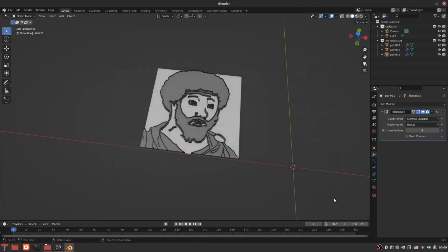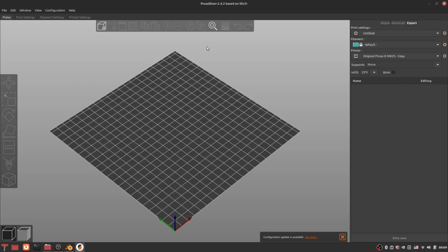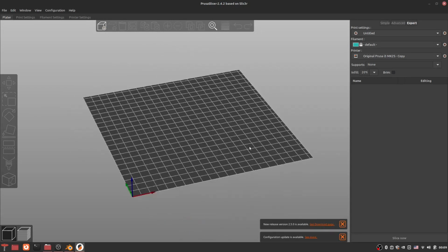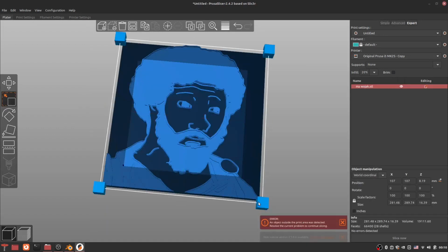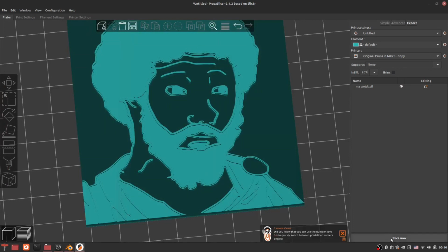The model is ready, but it'd be nice to check if everything is alright, so let's open Prusa Slicer. I will, you might enjoy something else. Here we don't care about optimal print options yet, we just want to check if the model is readable and is interpreted correctly. So let's open it, resize it so it fits onto the build plate and press Slice.